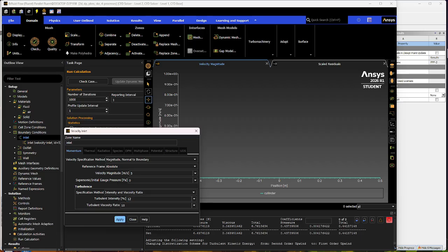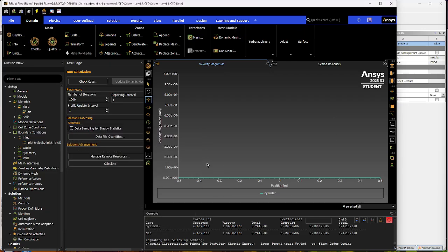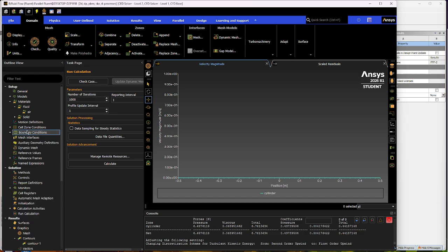That gives me a Reynolds number of approximately 821,000. So that's good. We're well beyond the critical Reynolds number of 500,000. So that's good to know. And we're going to close out of that.